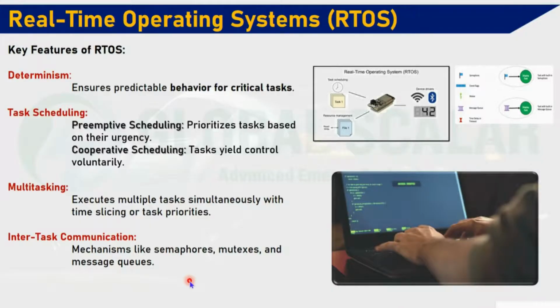One should be locked if the other is not utilized. So it is a part of inter-task communication, how it is able to handle the tasks at different times. And we have interrupt handling: if any hardware or software interrupt is triggered, that event should take the responsibility of updating such data. So that is a part of interrupt handling.